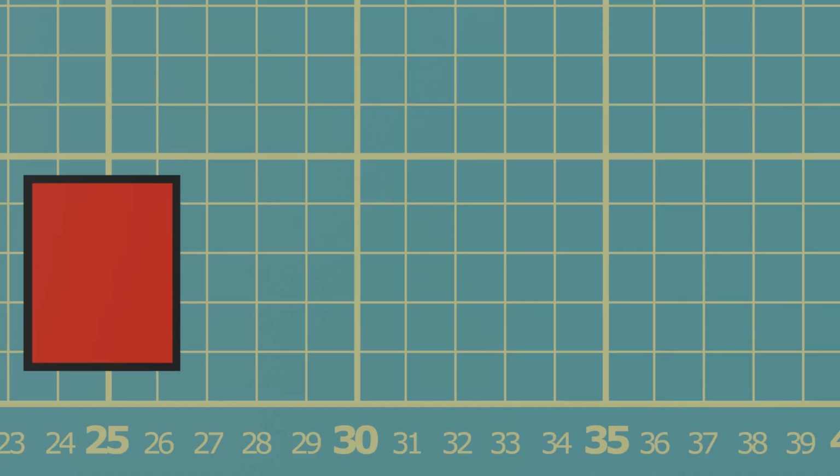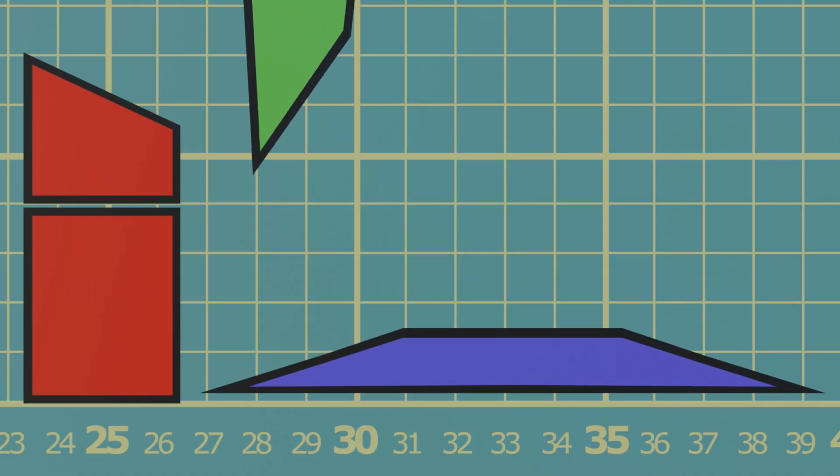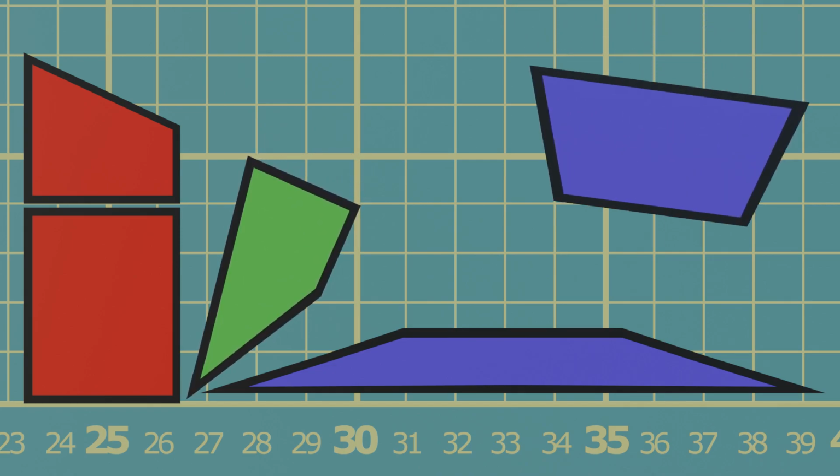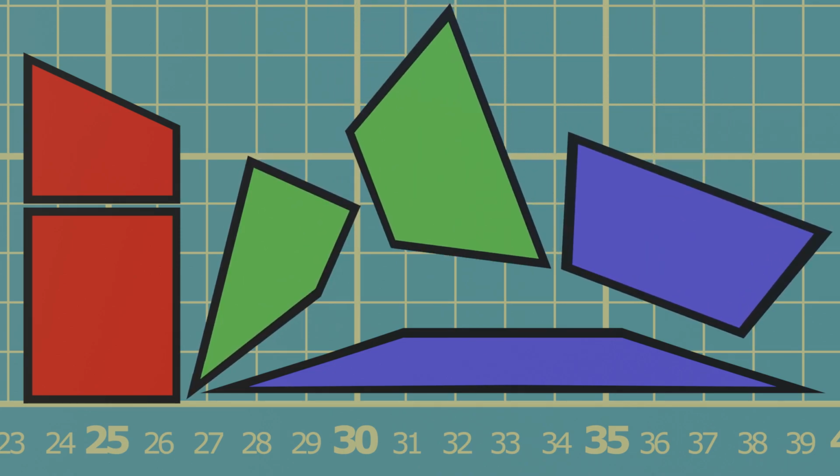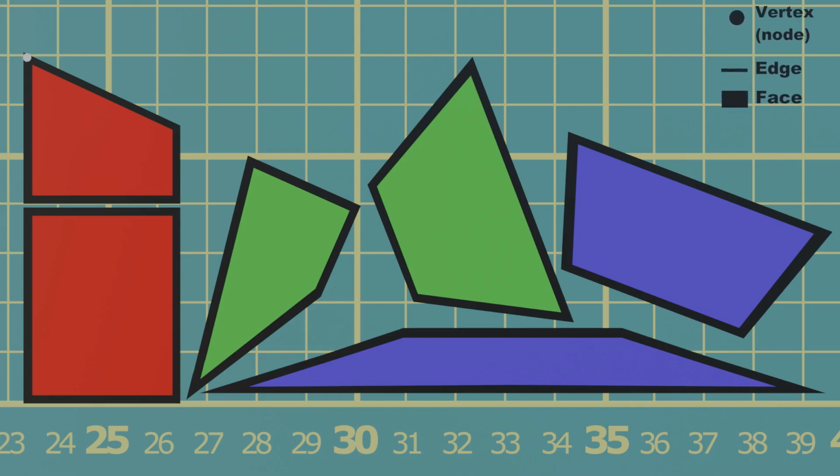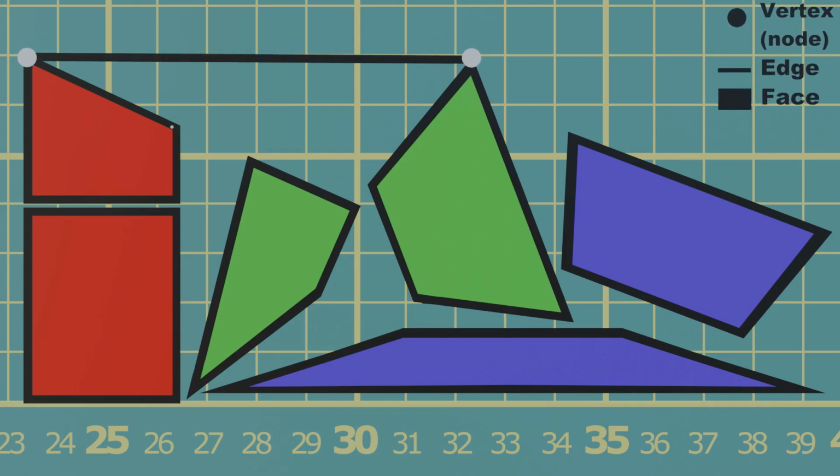For good topology, a quad-based mesh is preferred. What are quads? These are faces with 4 sides. They come in various shapes. I included 6 of them. All 6 of these are quads. If we create a face connecting the various quads, we get a so-called n-gon. N is for many, or more than 4.